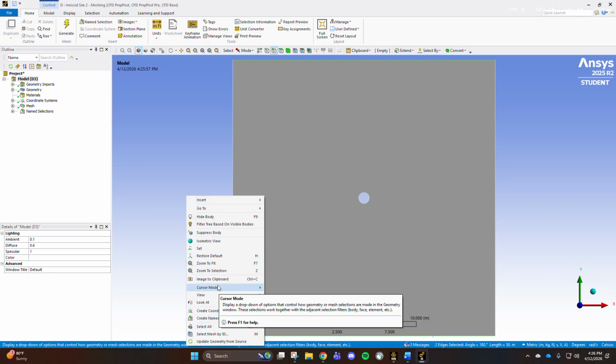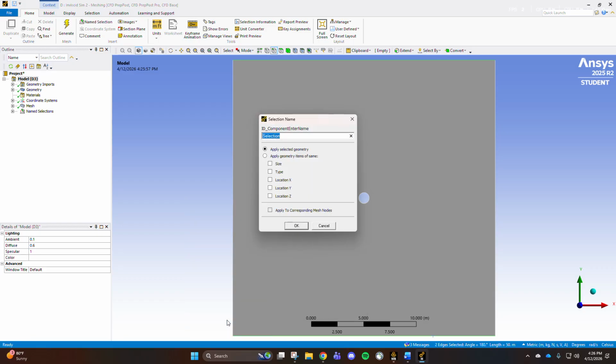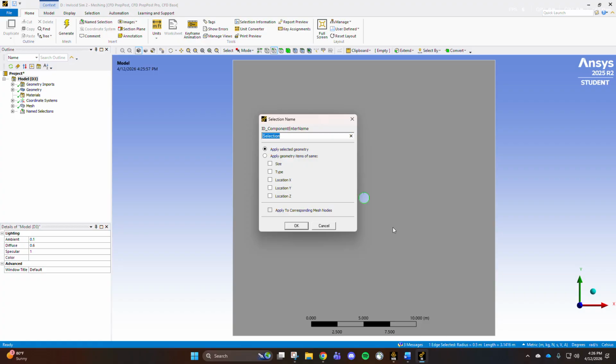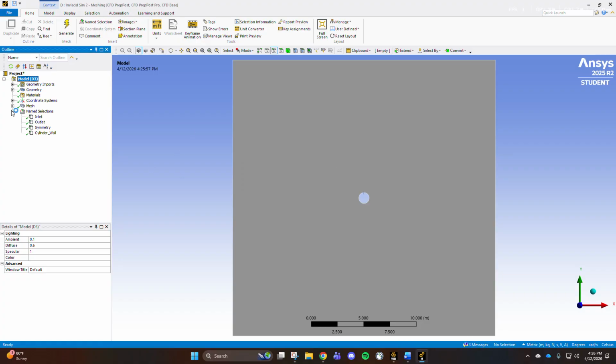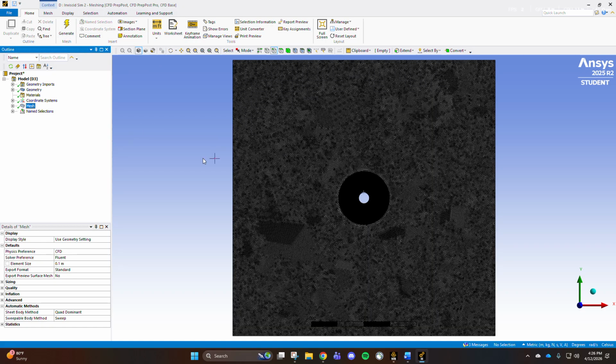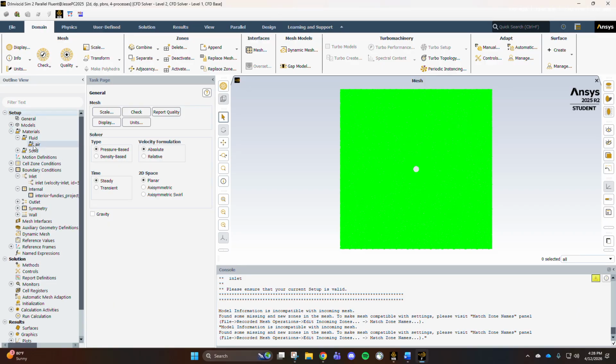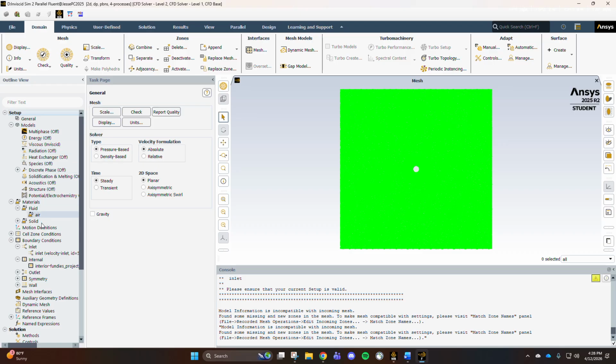These aren't really walls. And finally, our cylinder, which will be cylinder wall. Name selections look good. Amazing. Click generate again just to make sure it works, and it does. Mesh looks good. We're going to exit out of there, and I will see you back where I left off in setup. Okay, so we're back in the setup, and our model is still Inviscid.